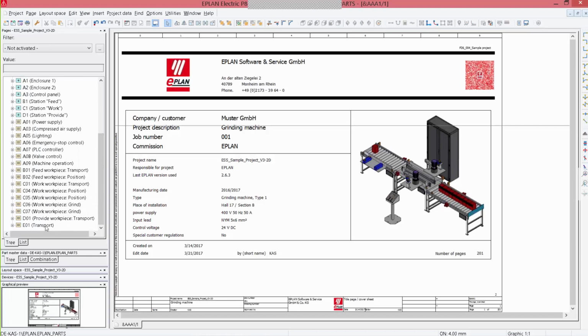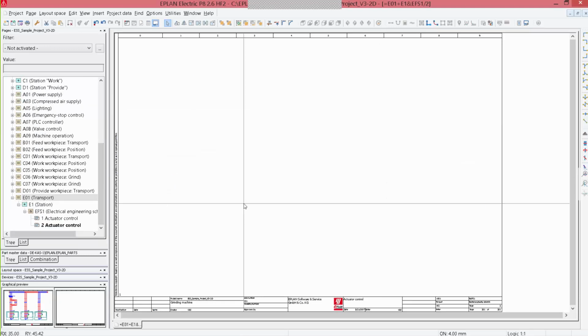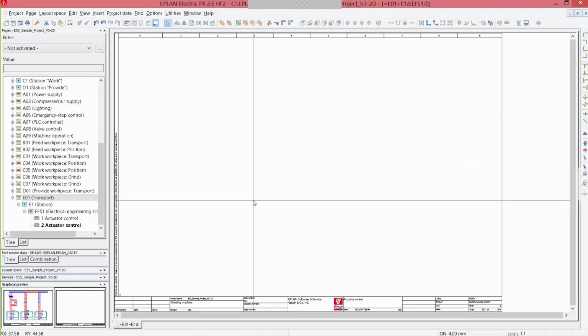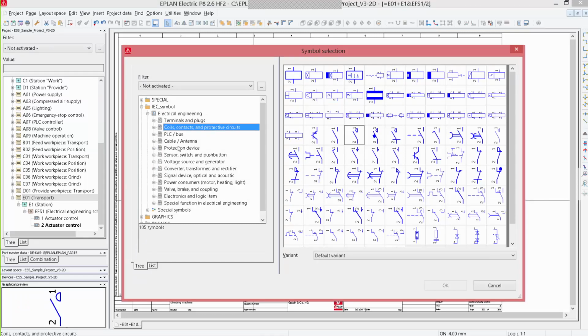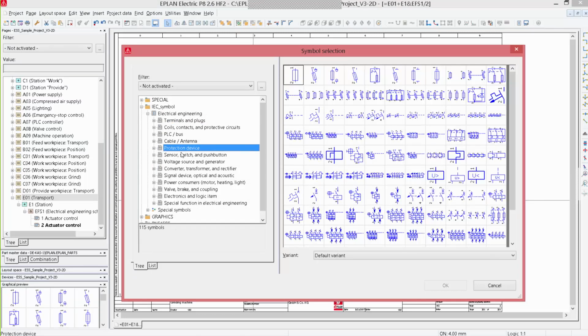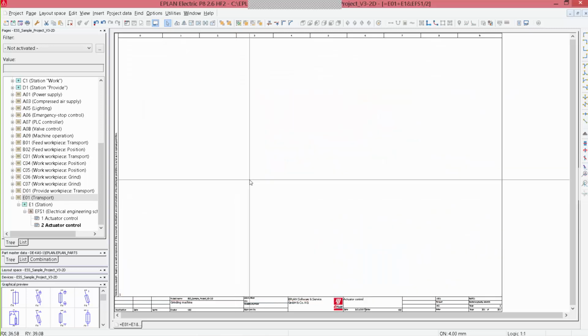So when you talk about, for example, creating a complete empty page, you have, of course, the capability of different flexible design methods, like just traditional symbol-oriented design, which is known by most, utilizing symbol libraries to build the different schematics accordingly. And later on, of course, you may also add part numbers to be able to generate a bill of materials in the very end. All this is fine, of course, but I would like to give you some other input on design methods. Once you build certain circuits, you also find that you very often reuse them. And instead of doing, let's say, copy and paste, we can also talk about typicals, reusable typicals.